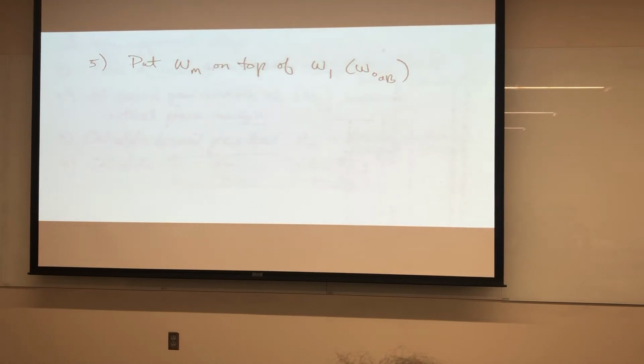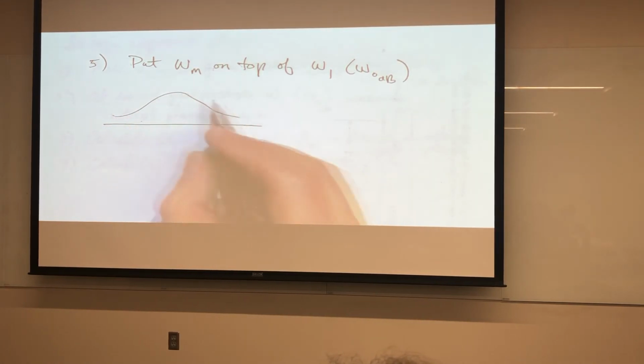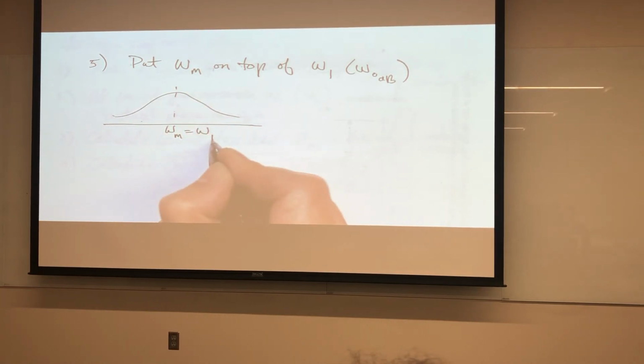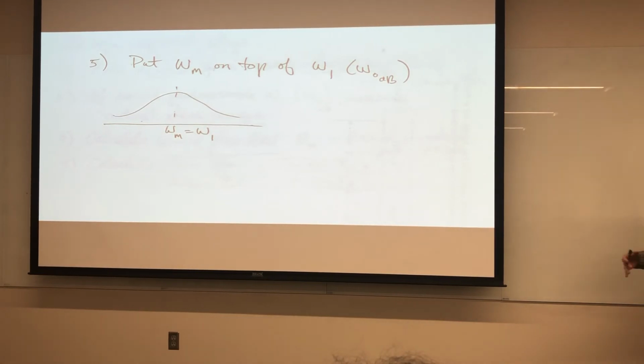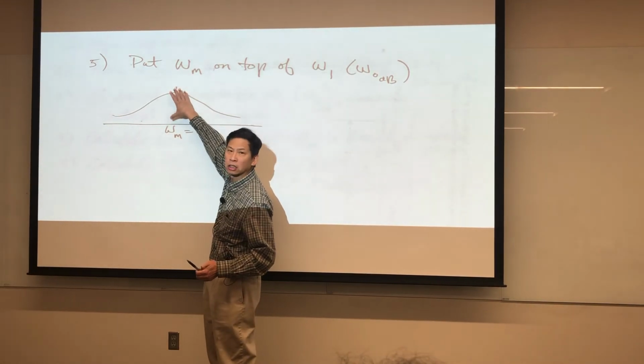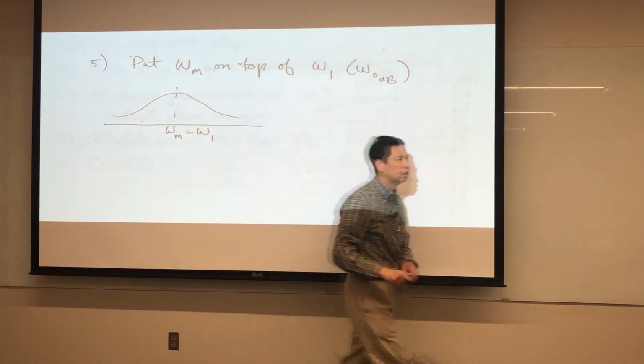Okay. Basically what we want to do is where I need the extra phase, I want to put this omega m equal to the right where I want the desired gain crossover. Because that's where I'm making the desired phase margin measurement. And so if I'm going to put a pile of dirt, I need to put it right on top of where I need the phase.